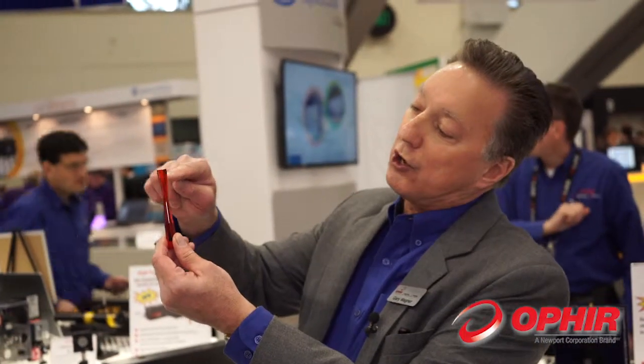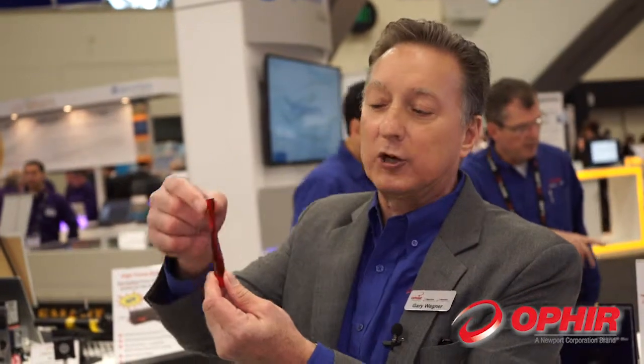That's exactly what we're doing with BeamWatch. We're imaging the Rayleigh scatter. So by imaging that Rayleigh scatter, we're able to actually measure the whole waist and caustic of the beam, looking for the spot size and looking at the spot shifting through the critical startup phases of any laser process.